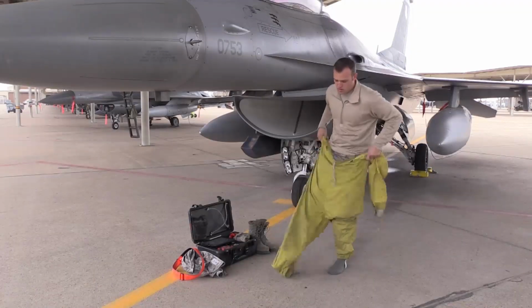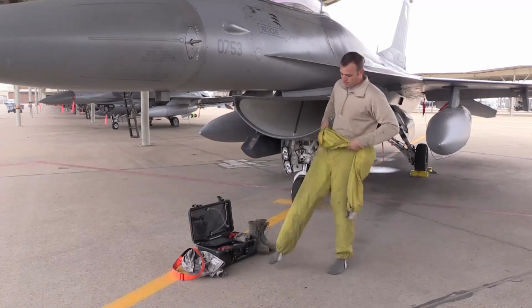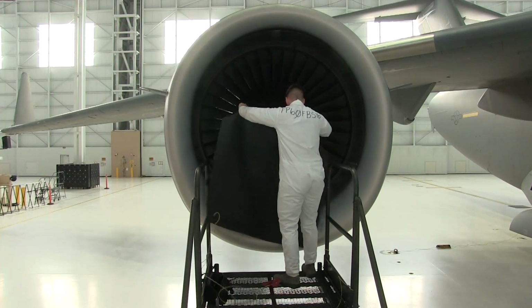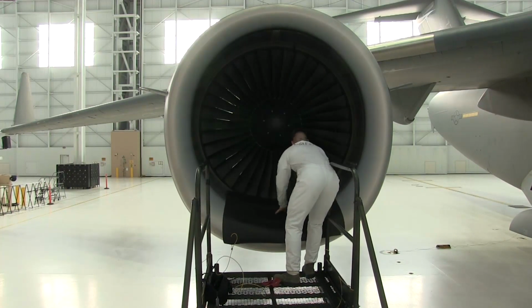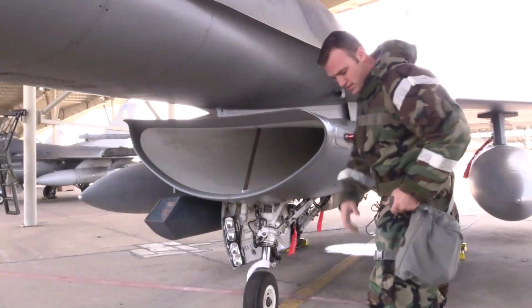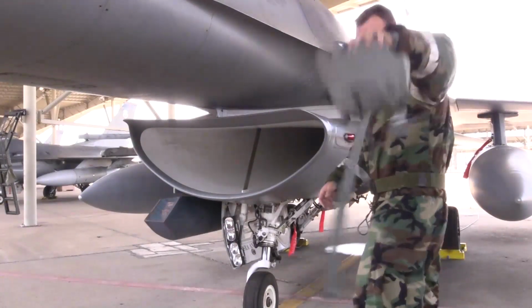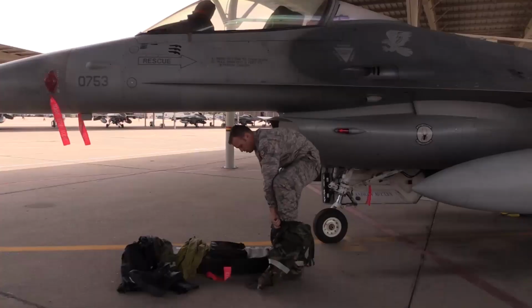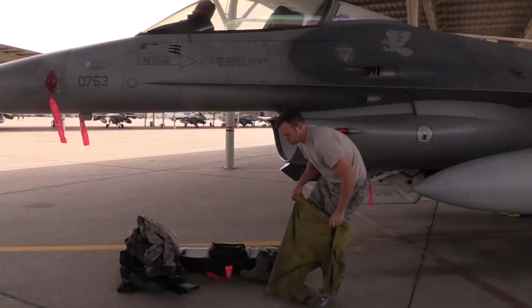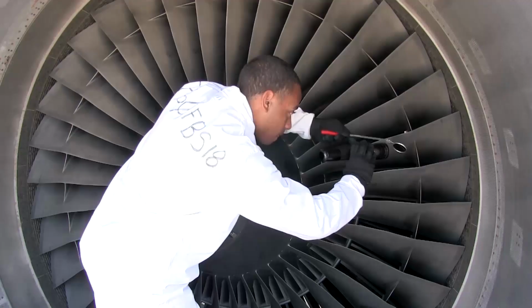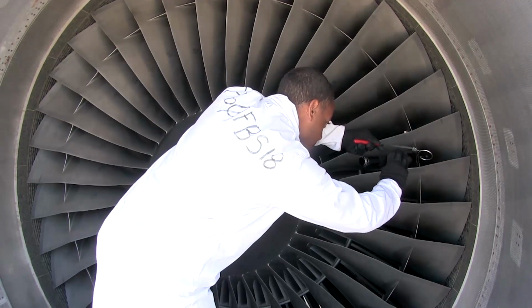Technicians will remove restricted area badges and empty their pockets prior to intake, inlet, and exhaust inspections. Wear a pocketless, zipperless, buttonless bunny suit with overbooties or stocking feet. A mat may be used in place of overbooties. When wearing chem gear, account for all necessary tape on zippers and remove accessories prior to intake inspections. During exercises, remove chem gear and utilize a bunny suit.